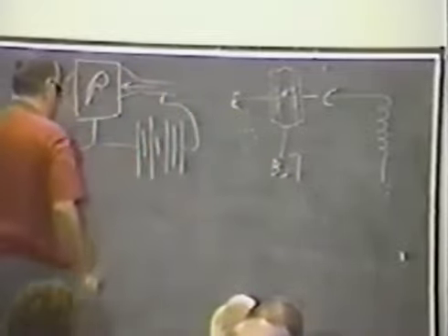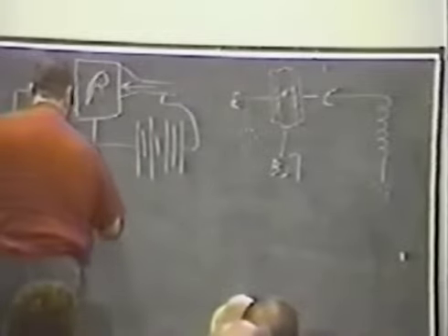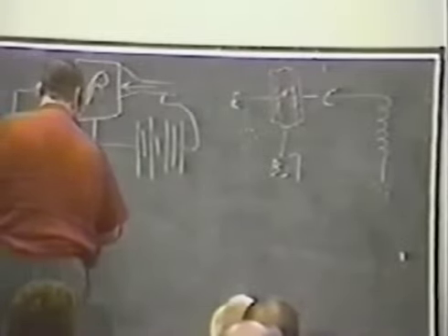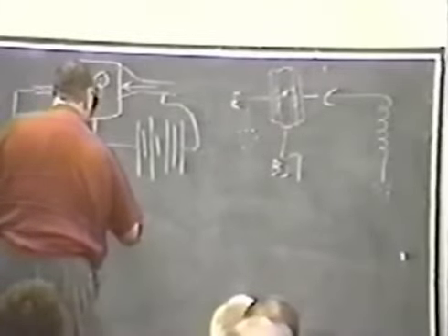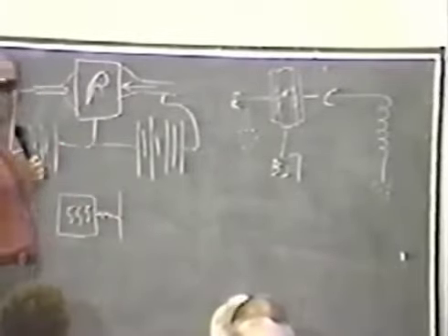What do we do with this thing? Take this thing, connect it to, as Al was saying, a 555. Put a current limiting resistor so we don't blow the hell out of the base.